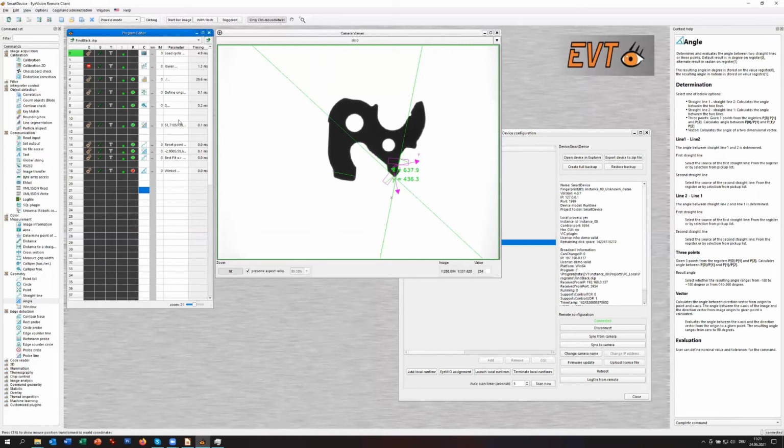You have to have one position where you can determine the line. If you have multiple positions, then you could add after reset multiple of these rect probes to the program, and these rect probes are then collecting the points into the point register.